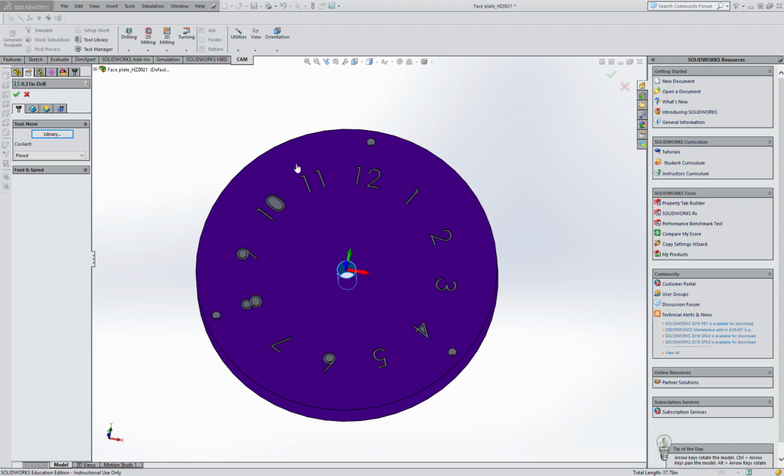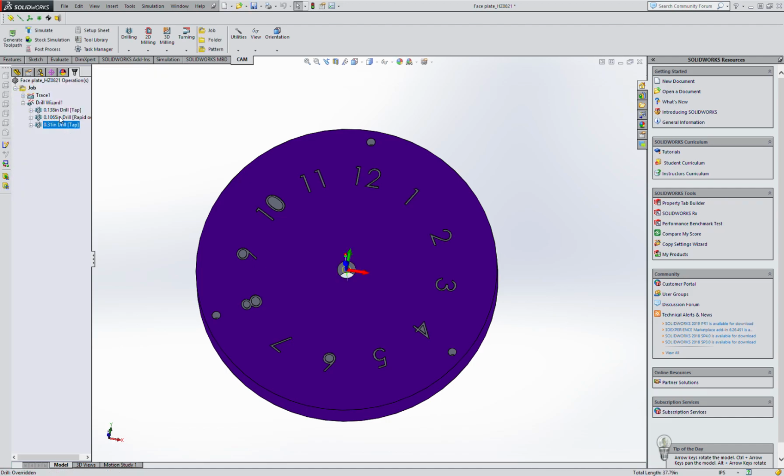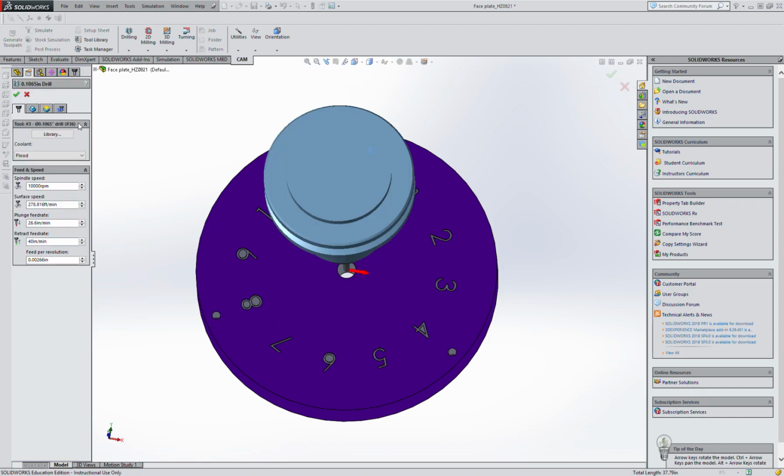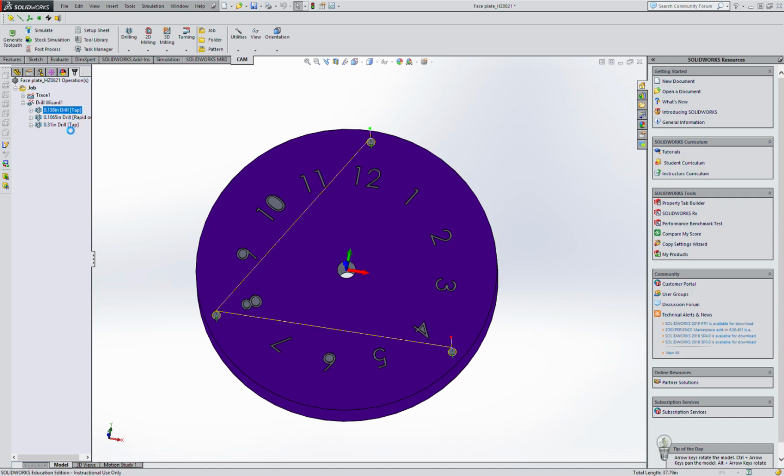Make sure this time we go down to tabs NC and 6-32. Click on select. Now the tool is shown here, and you can also define the spindle speed. We can choose 500 RPM here, and then click OK. Then you can keep looking at other operations to see if you have your tool chosen. Now you can see all the tools have been chosen. Same thing here. Alright, so we are good.